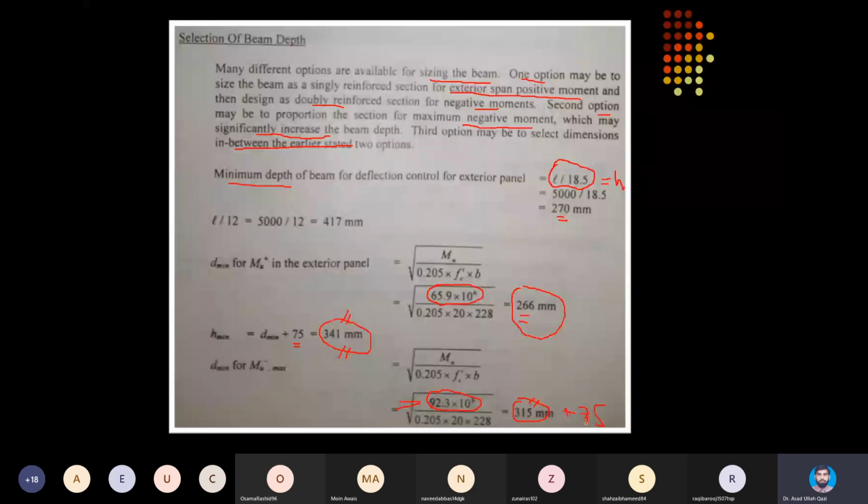However, if your neutral axis depth falls within the web, then at section 4 and 5, you need to call the design methodology of T-beam, in which the couple will be made between steel and the flange concrete and steel and the web concrete.